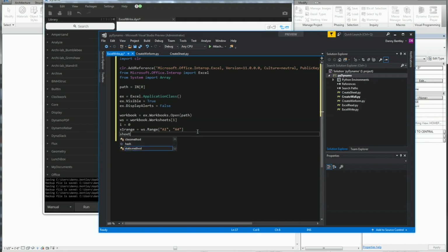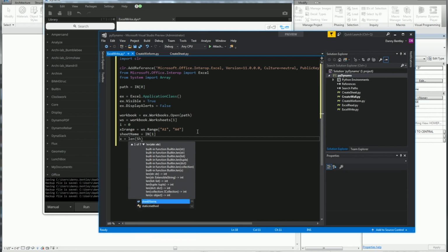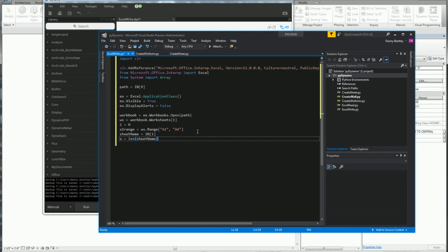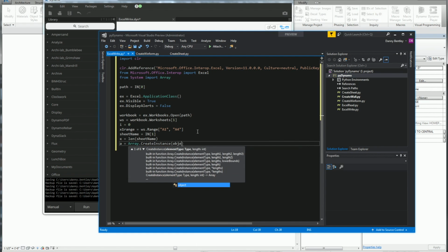And in this one, I'll go ahead and add a second input into my node, which will be my sheets. They won't come in in any particular order. They'll just be sent in whichever way that Dynamo sends them in. The great part about this is I can get the length of that list. So however many sheets that I've got, it'll give me a number for X.